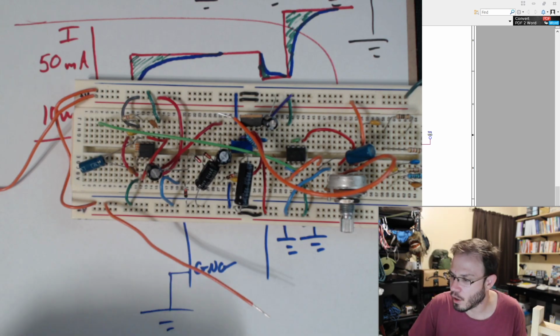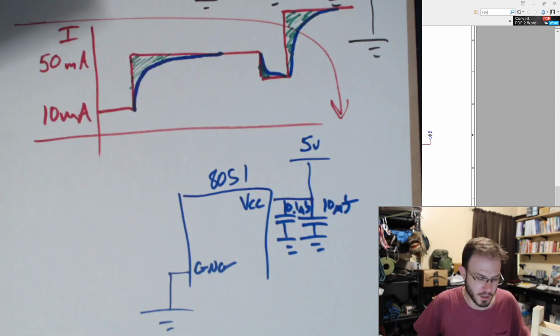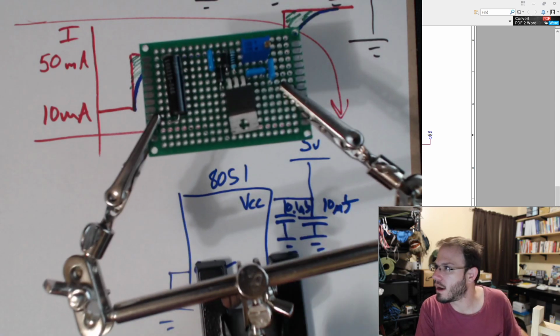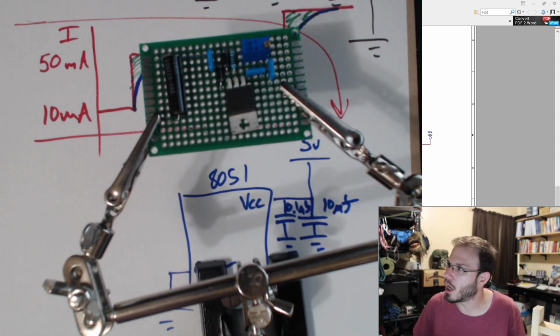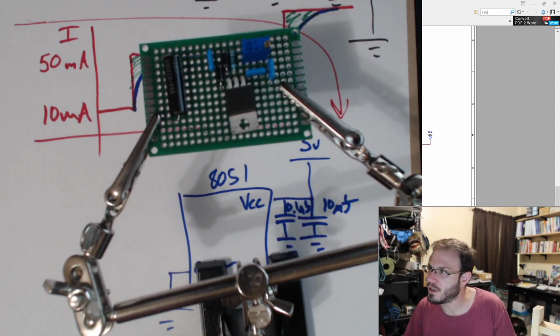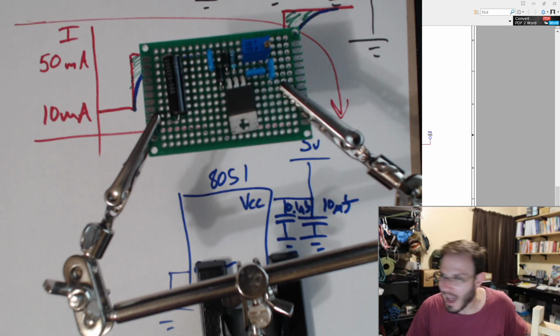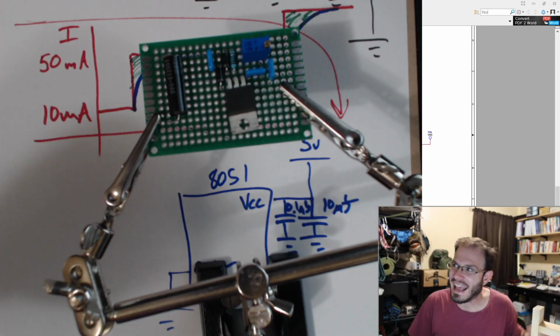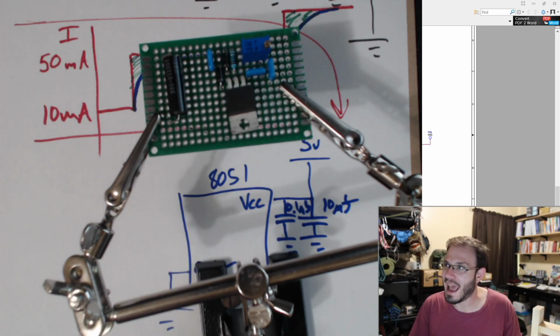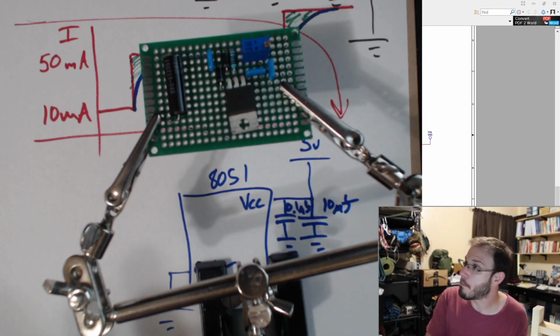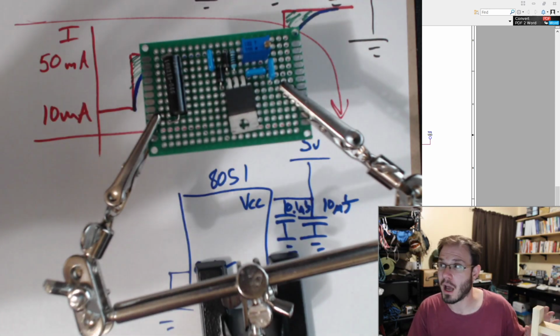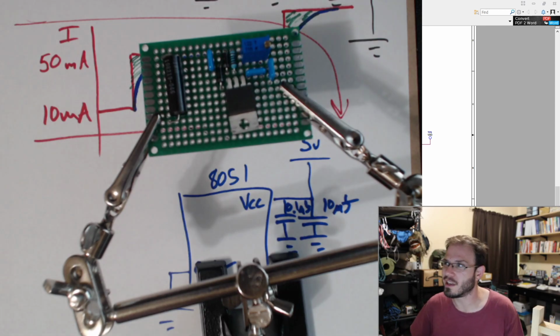But when I go to a more finished product, my wires all of a sudden become shorter. That's going to be less of an issue, but I'm going to put those bypass caps in anyways, and it's going to be even less noise than I measured, and what I measured was tolerable, so I should be in a really good safe place.